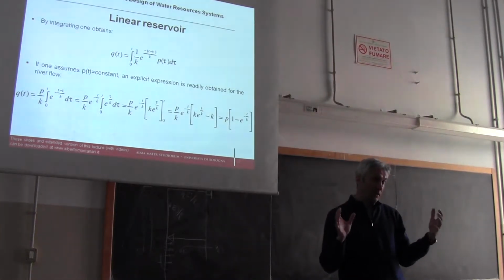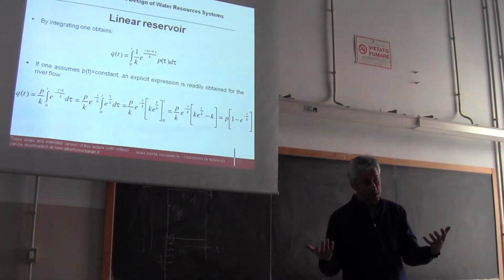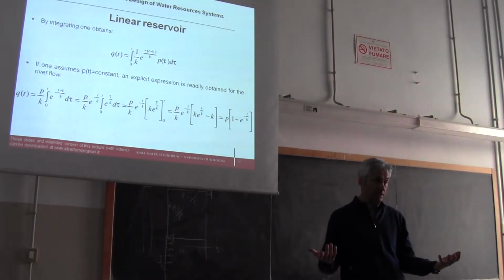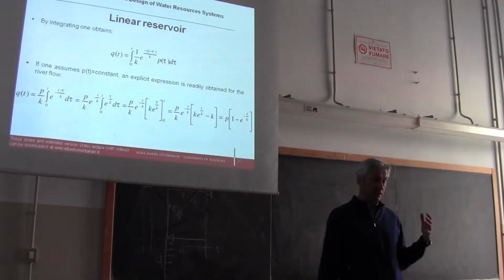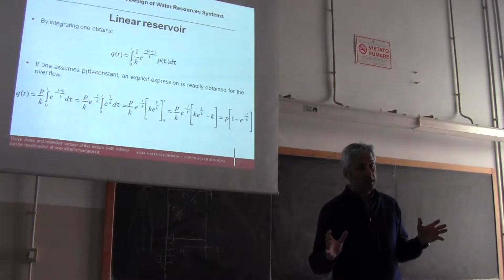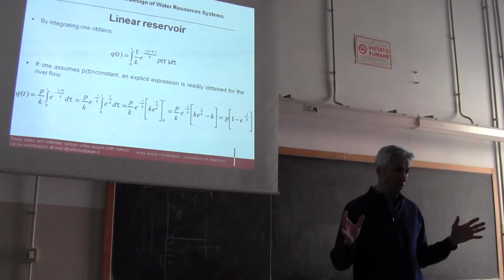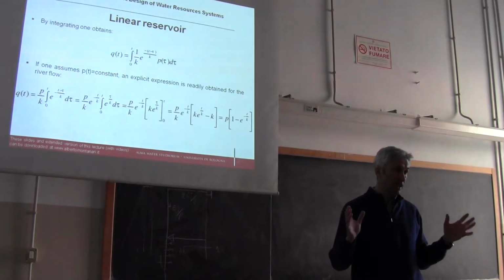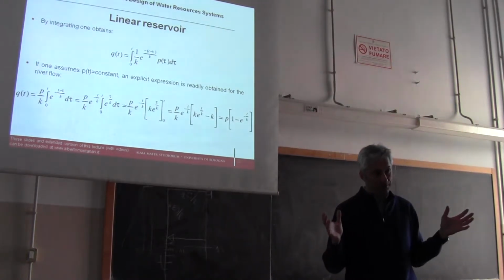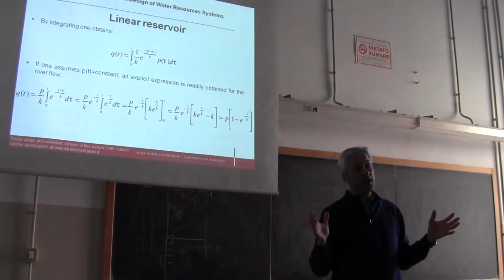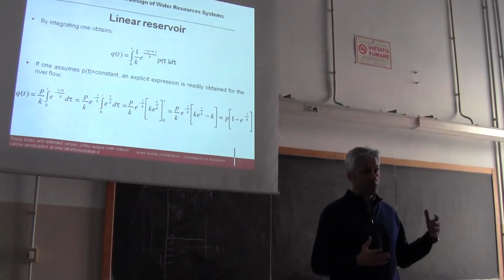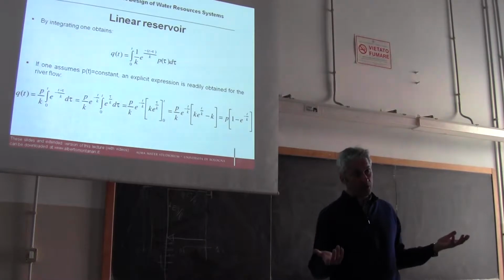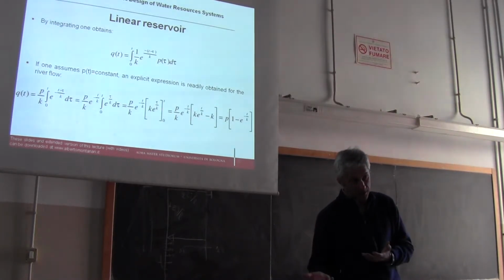You can neglect evapotranspiration when other flows dominate over evapotranspiration. And in this case, the other flow that you are considering is river flow. And what are the conditions where river flow dominates over other flows? These conditions are those in which the river flow is high. Of course, it's intuition that suggests you that when a river flow is high, it's very relevant. You can neglect other flows. So during floods, of course, you have a high river flow, and then you can neglect evapotranspiration.